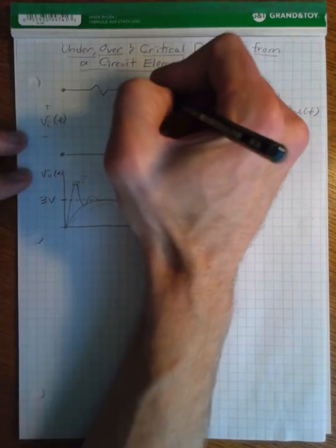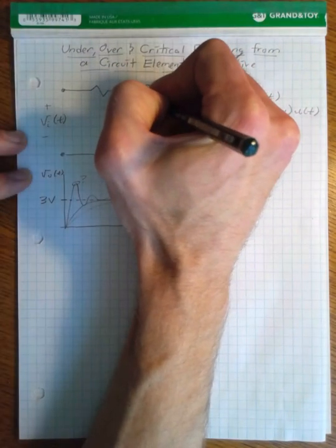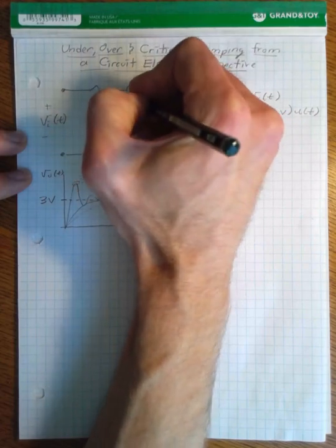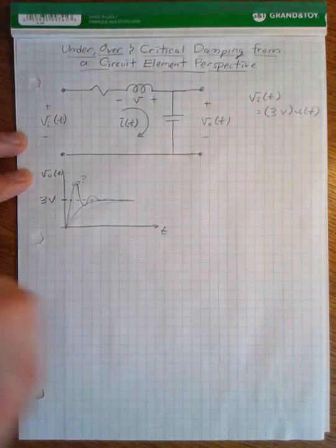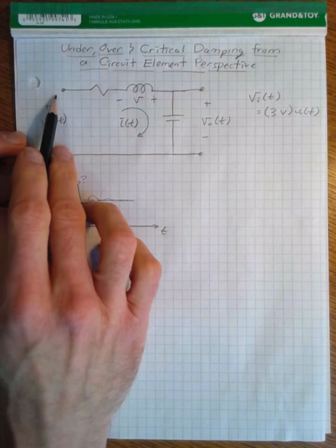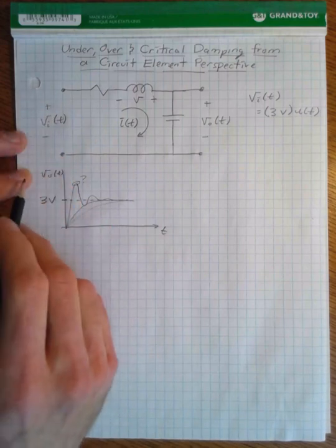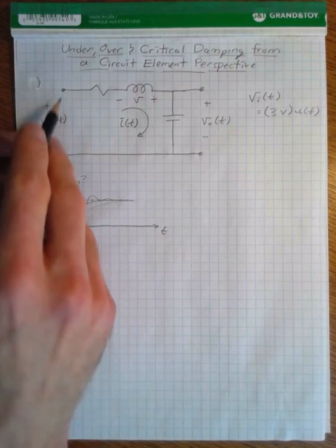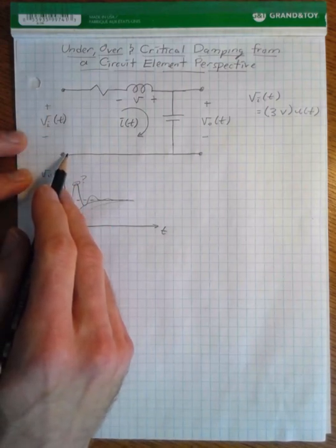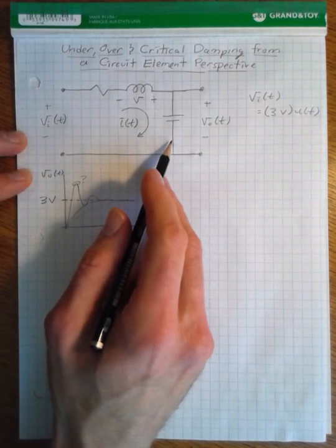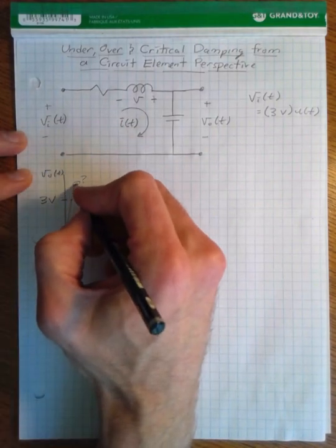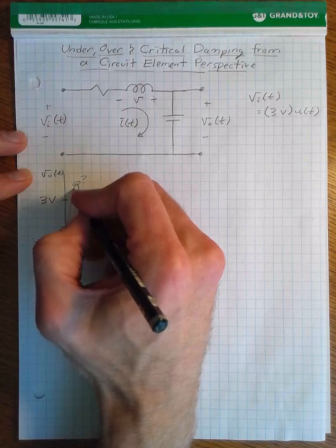And so it actually creates a voltage across itself that will add to the source voltage in order to keep the current flowing in the clockwise direction. And so it will essentially add in series to the input voltage and will produce a higher voltage across the capacitor, and will basically overcharge the capacitor. And so that's why our voltage keeps on shooting up, up, and up.